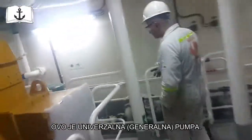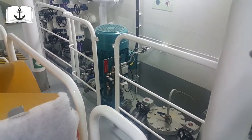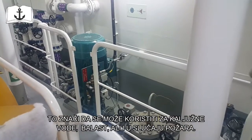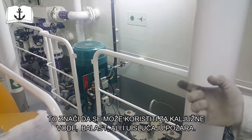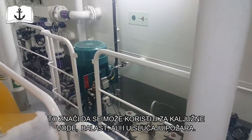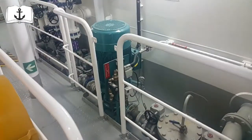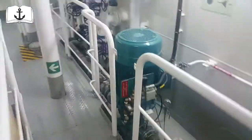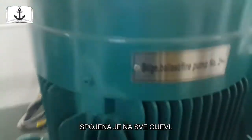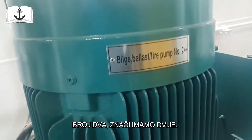Yeah. This is like a general service pump. General service pump, what does that mean? It means that we can use it for the bilge system, and also for the ballast system, and we can also use it for the fire system. So we can use it for anything we want. But the important thing is that it is connected to all the pipes. There is a filter. Bilge, ballast, fire pump number 2, which means we have number 1 also.